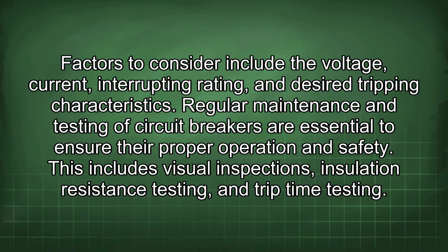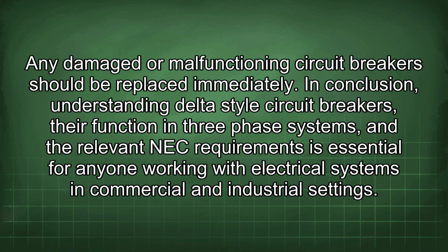Regular maintenance and testing of circuit breakers are essential to ensure their proper operation and safety. This includes visual inspections, insulation resistance testing, and trip time testing. Any damaged or malfunctioning circuit breaker should be replaced immediately.